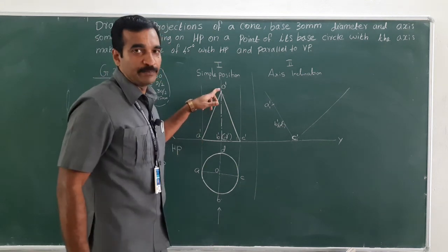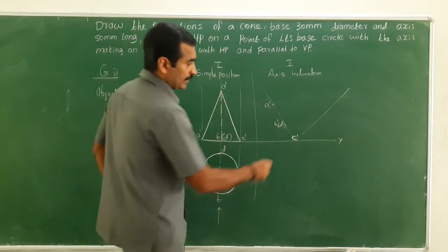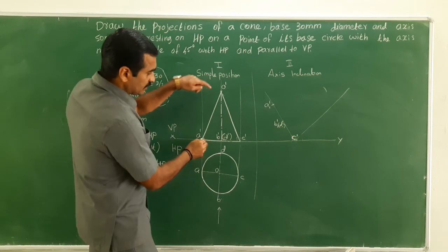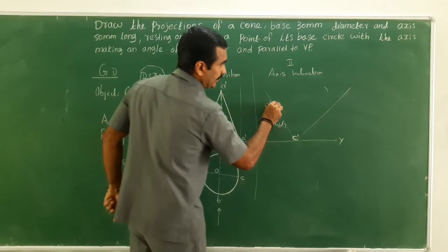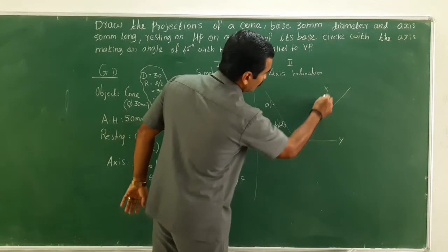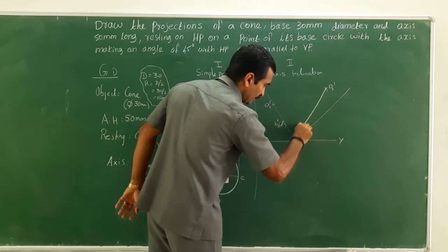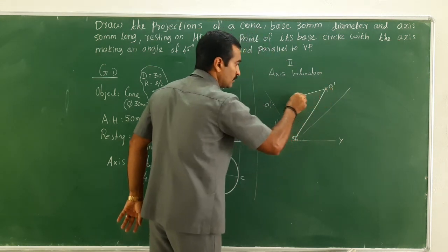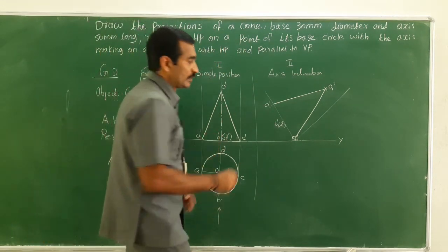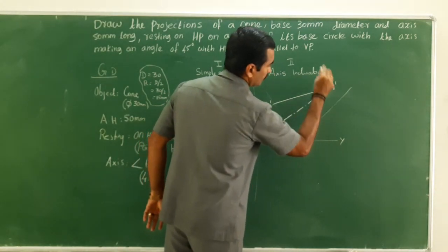Now, how can O be achieved? Measure the distance from C to O in your compass. Keep it at C, cut an arc. Similarly, measure the distance AO. Keep it at A, cut an arc. That's the intersection point. Right? Now, this could be O1 dash. Connect O to C and O to A, and B to O with the axis line, long line dot long line, like so.